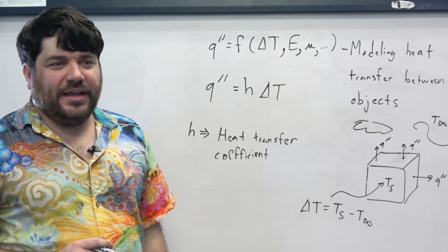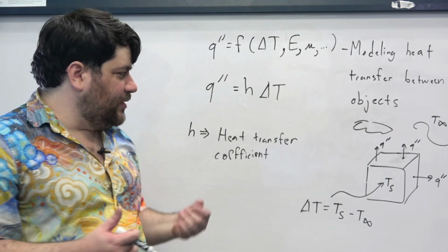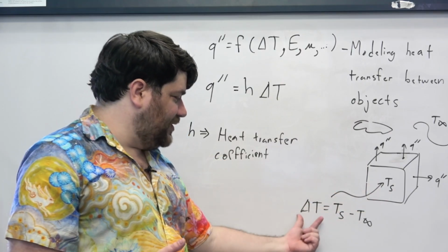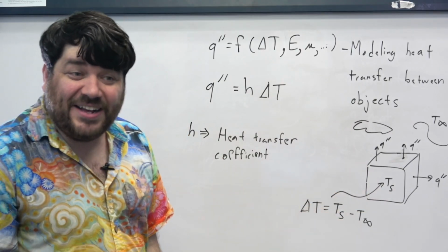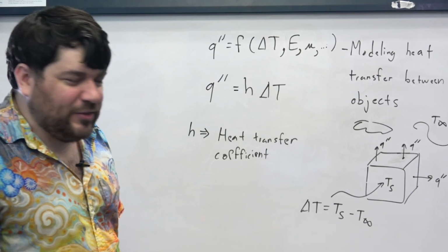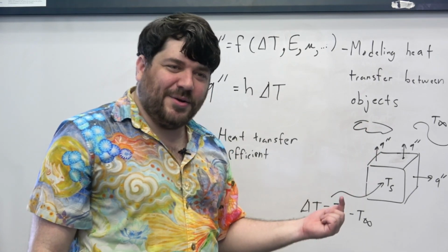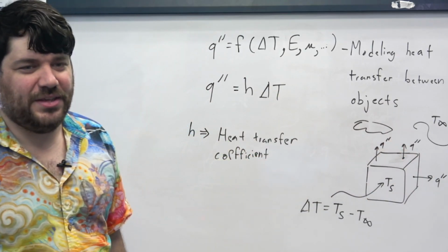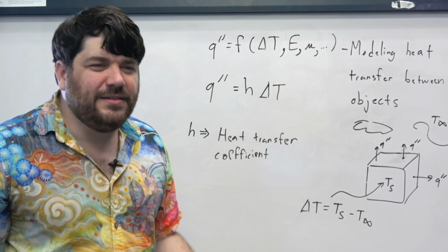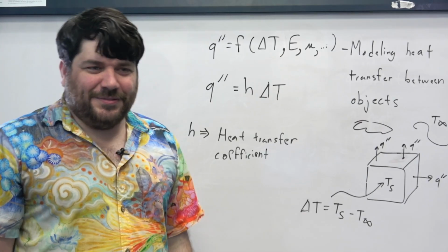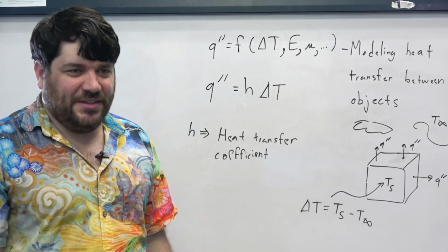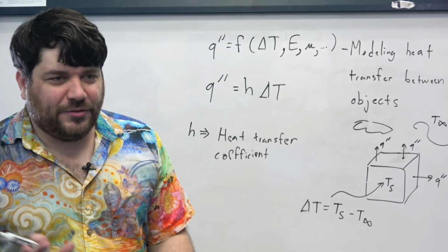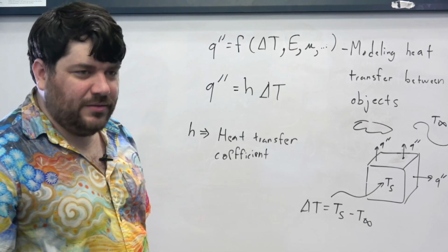And in this particular case, it's very easy to do, again, because all we have to do is investigate whether this difference in temperatures is positive or negative. And then based off of that, are the heat fluxes going inside or outside? And this boundary that we've created between the object and the environment makes it easy for us to figure out what the inside direction and the outside direction are. Right? So we don't have to rely on any vectors or vector mathematics for now.